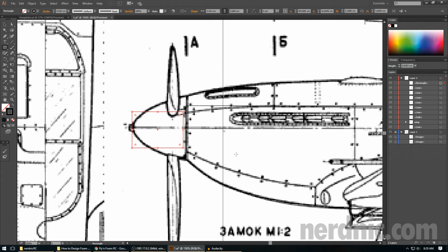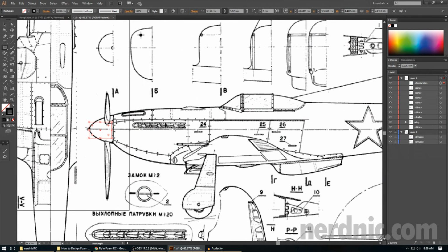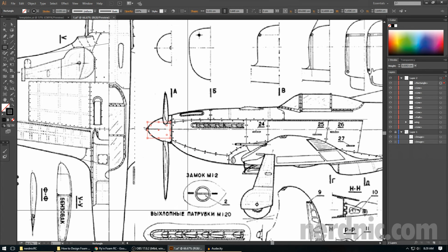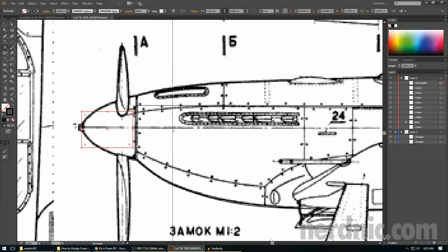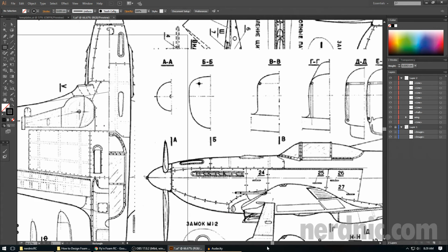If it is high or low, it usually doesn't change a whole lot. It will look different, and if it's really extreme, you will fly different because you're changing your thrust line, which is important relative to the wing and the tail and everything. But for most of the planes I've designed, you can line it up to where it fits, it works, it makes sense.